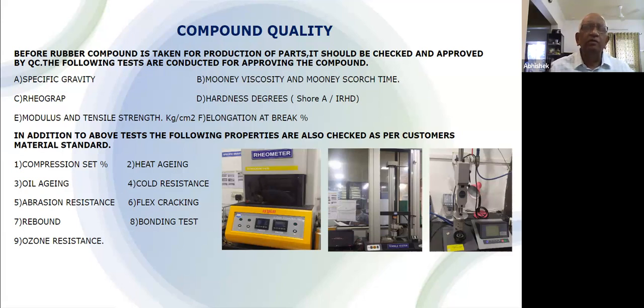This is basically nothing but monitoring the viscosity rise, or how the cross-linking will take place at a particular temperature. It is nothing but getting the graph of torque against time at a particular temperature. For example, if I have a mix and my processing temperature is say 170 degrees centigrade, this is the rheometer, which I will set at 170 degrees centigrade. And then a small 5 gram sample is put in between this. There is a rotor here. Put this here and close it.